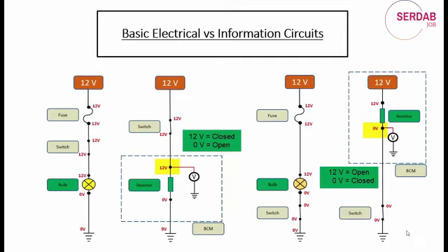Now for us, when we're diagnosing them, we just need to know if there's a fault in that circuit, or why the module is not turning on a circuit. Maybe it doesn't think that the switch is being pressed, or maybe there is actually a fault in the switch itself. Diagnosis becomes more of a three-part process because you have an input circuit, the circuit that provides the information, you have the module or the decision maker circuit, and then you have the output circuit or the device that is being activated, or the load that you actually want to work, like a relay or an injector or whatever it is.